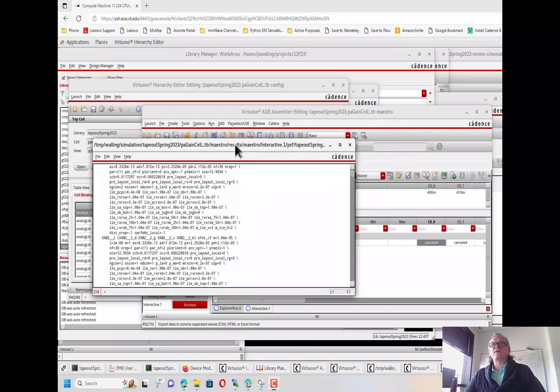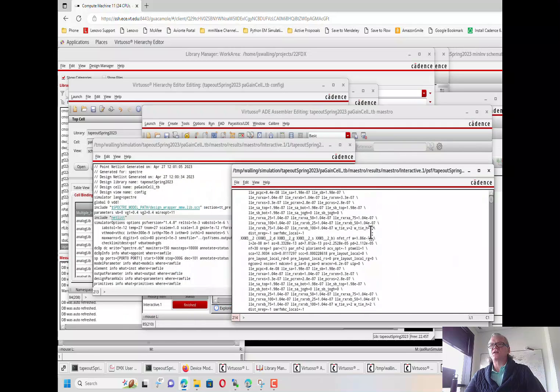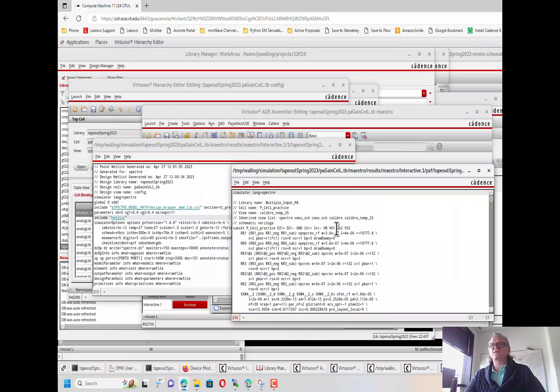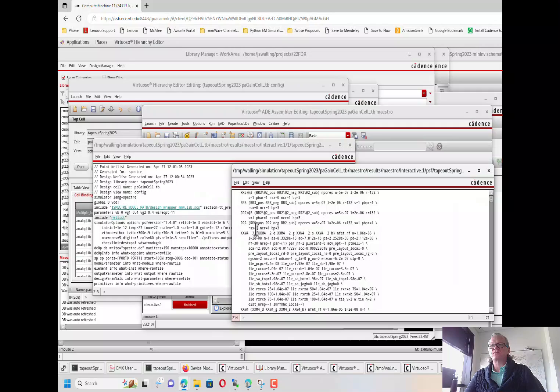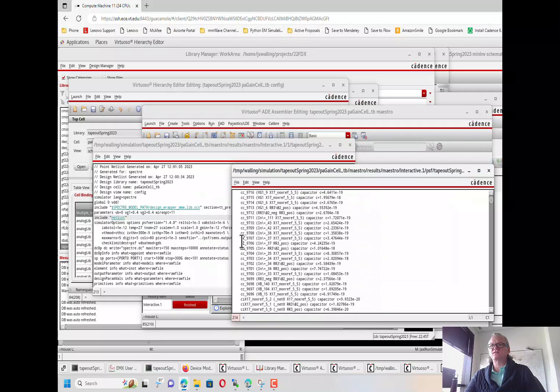All right, so I've just opened the netlist again, and just to take a look to show you that the netlist, in fact, after we changed to the Calibre view, did change. And so now if we look at that P-cell practice, we can see not just the normal schematic components, but there will also be a lot of other components in the netlist, all these capacitors, which are parasitic capacitors that were extracted during the Calibre extraction.